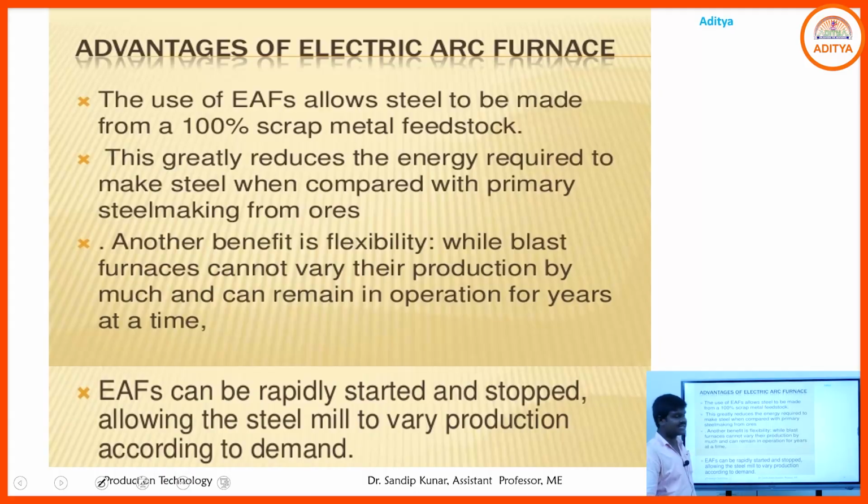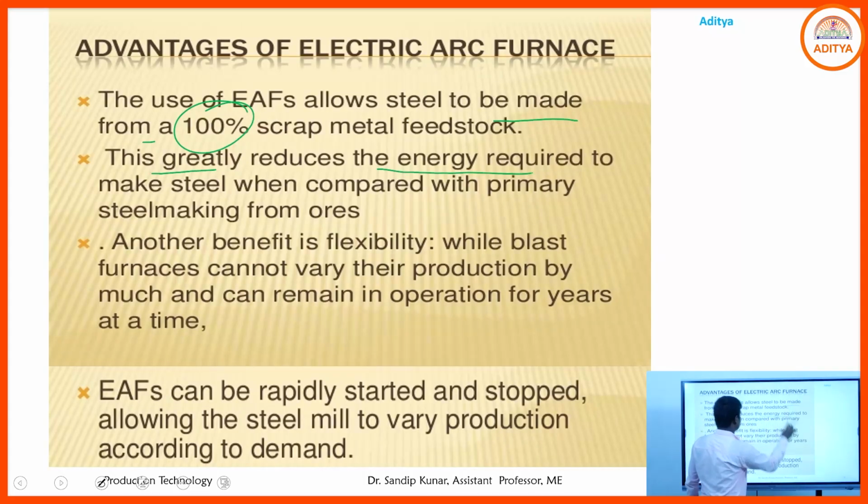What are the advantages of the electric arc furnace? First advantage: in an electric arc furnace, steel can be made from near 100% scrap, which will be converted to 100% liquid molten metal. Second, its use greatly reduces the energy requirement. The requirement of energy also reduces in the electric arc furnace.